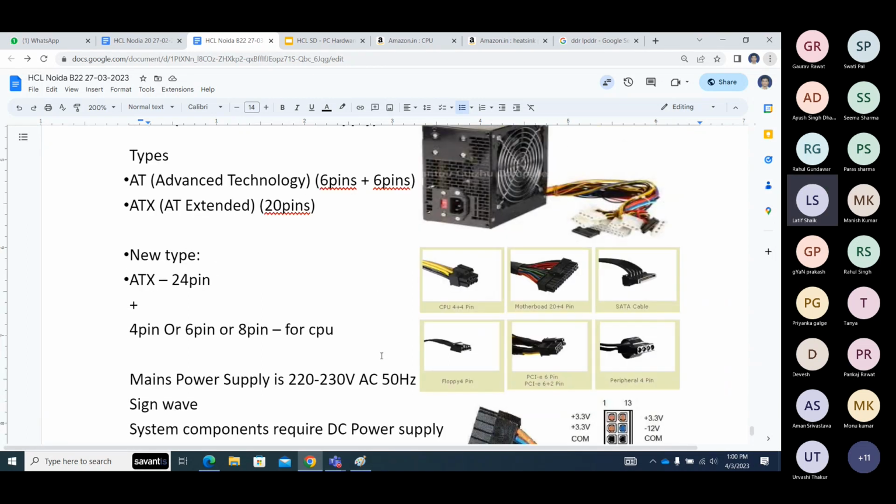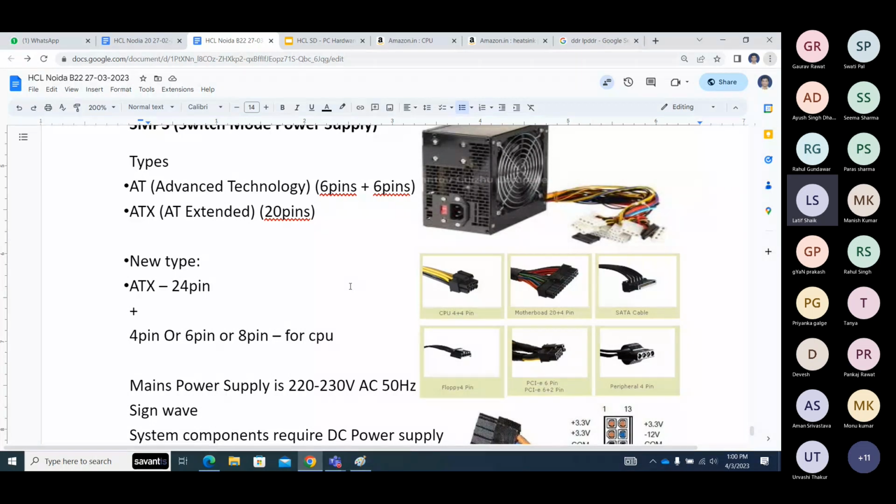And there is an additional power supply based on your motherboard. There is a 4 pin, 6 pin or 8 pin additional connector for a separate CPU power supply. Next, SMPS to hard disk, SMPS to DVD ROM, SMPS to your floppy disk if you have one from the olden days. Okay, a separate direct power connection. Hard disk, CD-ROM, floppy disk don't take power from the motherboard, only data connection. The power supply comes directly from the SMPS to the hard disk.